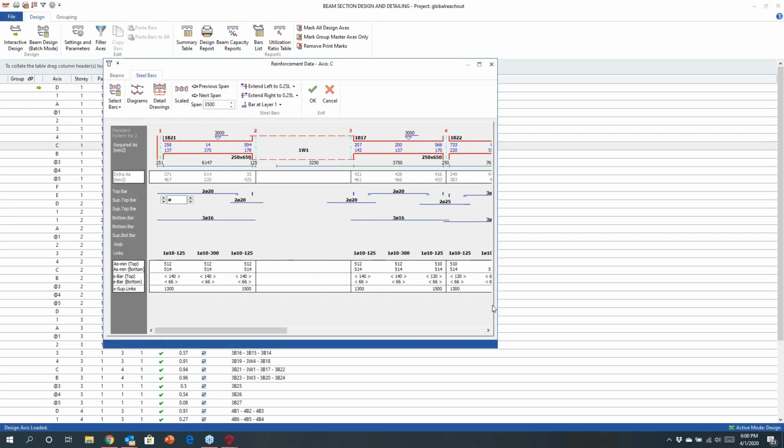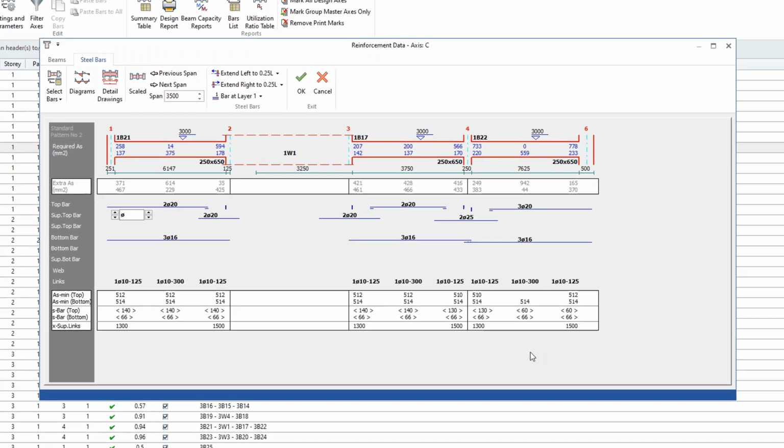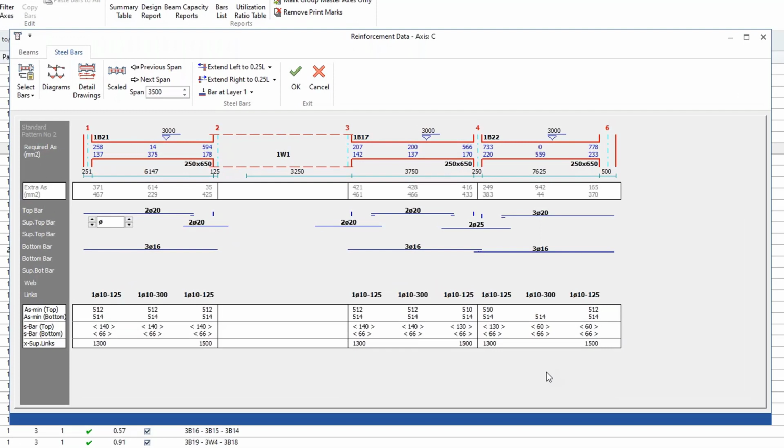So you can set up limits in terms of what you would expect to be acceptable or unacceptable loads that we don't cater for in design. So minor axis bending, for example, axial loads and beams are not normal. So what we do is we'll flag those to you. But this is optimize the design here. You can see a schematic of the reinforcement.